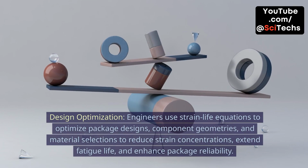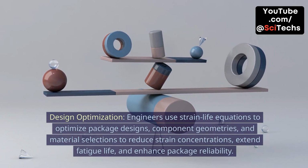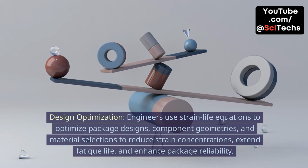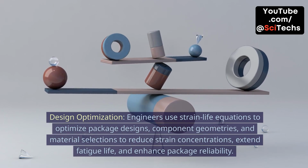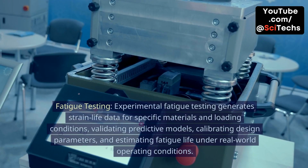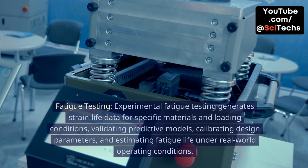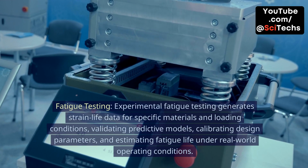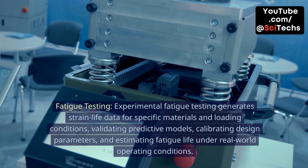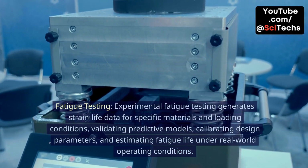Design optimization. Engineers use strain life equations to optimize package designs, component geometries, and material selections to reduce strain concentrations, extend fatigue life, and enhance package reliability. Fatigue testing. Experimental fatigue testing generates strain life data for specific materials and loading conditions, validating predictive models, calibrating design parameters, and estimating fatigue life under real-world operating conditions.